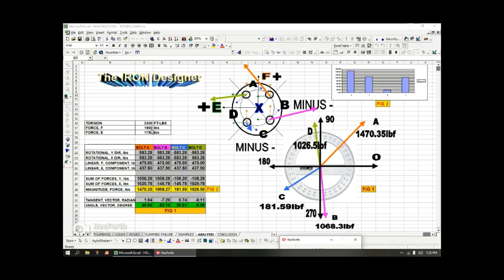And then you have the force F, which is this one, and I'm saying that it is a vertical force, and it is 1,900 pounds, and I colored that in orange, and here's the orange vectors for F. So I'm assuming that each of the 4 bolts are all equally distributed and symmetrically carrying the load equally among the 4 bolts, and so I take and divide that by 4.